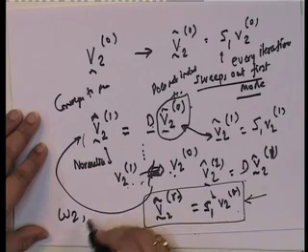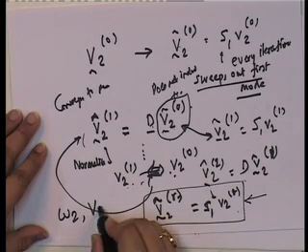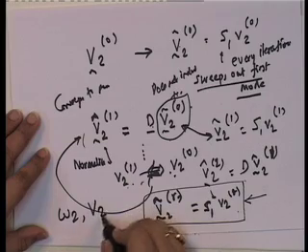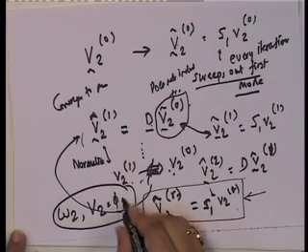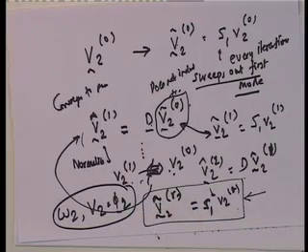If you don't sweep it out, you are always going to converge to the first mode. If you sweep out the first mode, every displacement quantity that you get does not contain the first mode, and it will converge to the second mode. So this way you can find omega 2 and your V2, which is effectively phi 2. This is how you find the second mode.